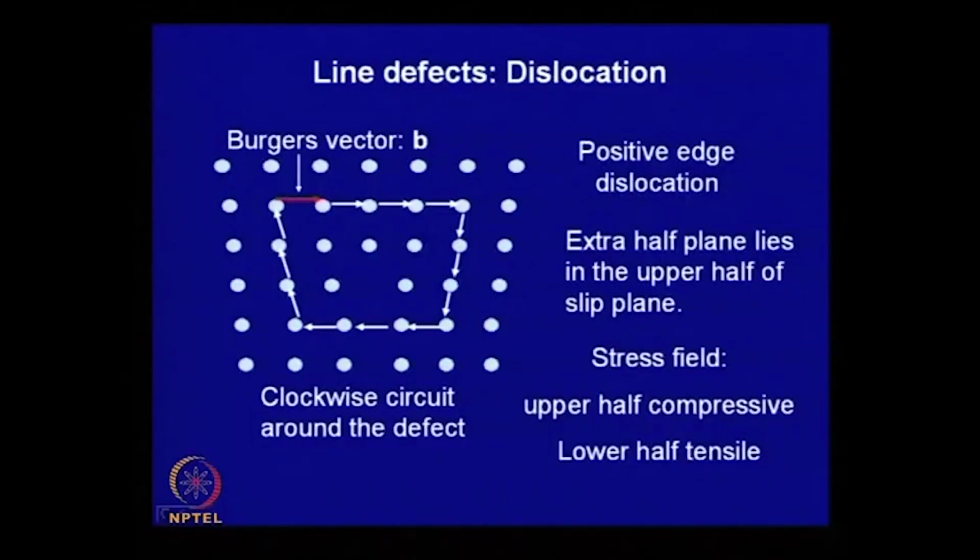The reason we do not get it is that the crystal contains a defect called dislocation, and this is a line defect. It demarcates two regions: it is a boundary between the slipped and yet-to-slip region. Now, let us look at the atomic structure around possible dislocations, which is shown here. This is a crystal, periodically arranged. See, these atoms are arranged along this line. It is a 2D crystal.